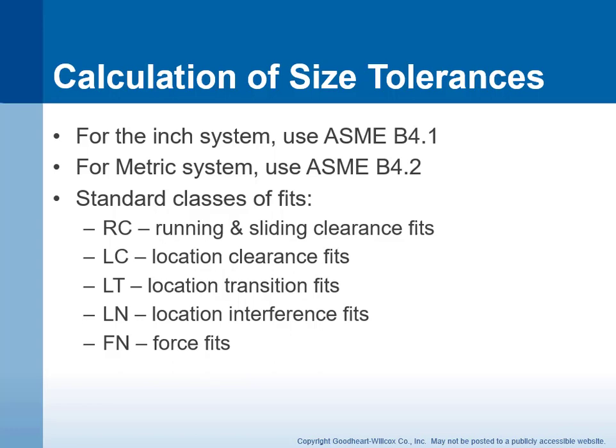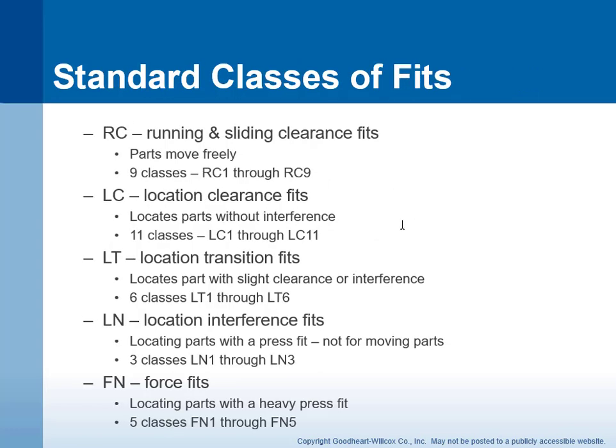So to talk a little bit more about these fits, if we specify an RN, a running and sliding fit, that is a clearance fit, which means the hole in the wheel is always bigger than the shaft. The parts will move freely on each other, and then there's 9 classes, and we're going to talk about those in a minute. LC is a location clearance fit. Again, it's a clearance fit. The parts always go together without interference.